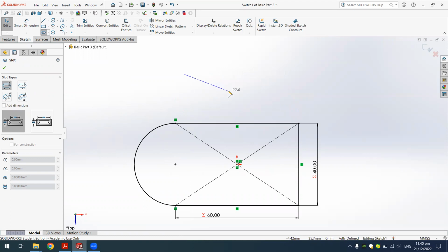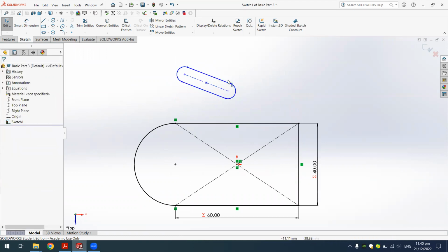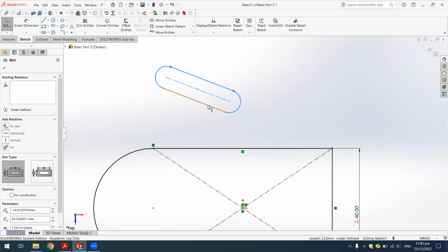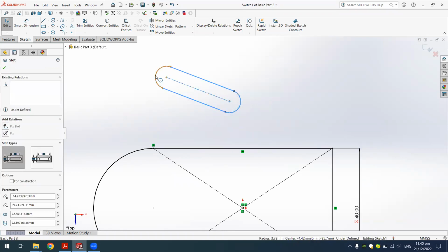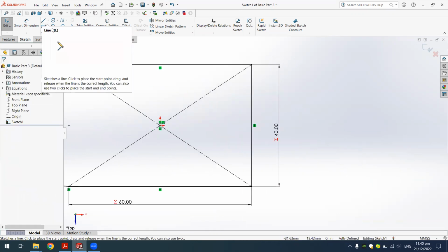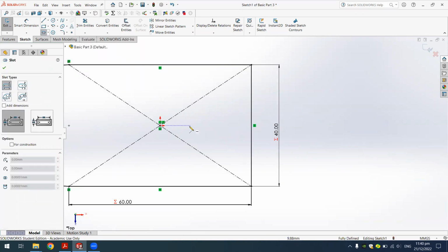It can be any line. Then after that, the slot will expand outwards like this. Basically, a slot is made up of two equidistant straight lines as well as two semicircular arcs, semicircular arcs that are tangential to the straight line. So in this case, we draw this arc.